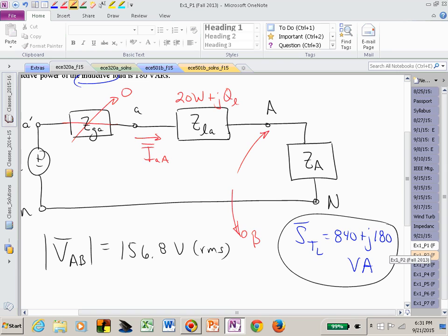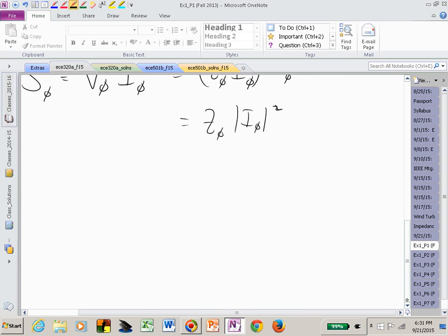So we can find the angle from this triangle, and then we could take the cosine of that angle to find the power factor of our load. What I just said is, from this information, we can say power total of the load is square root of 3 V load, I load, cosine theta phi.